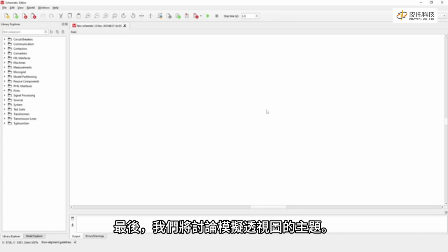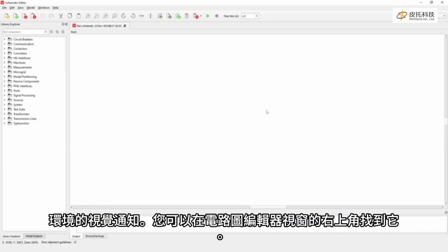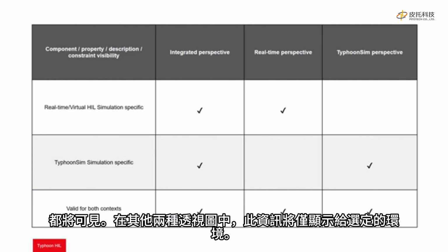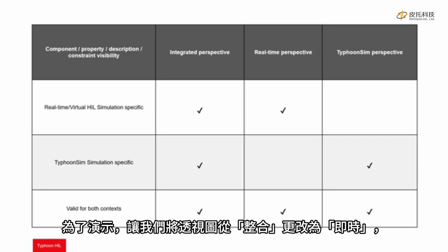The Simulation Perspective Chooser lets you focus on a specific context without receiving visual notifications from other contexts. You can find it in the upper right corner of the Schematic Editor window. There are three available perspectives to choose from: Integrated, Real-Time, and TyphoonSim. In the integrated perspective, all components, properties, descriptions and constraints for both real-time/virtual HIL and TyphoonSim simulation will be visible. In the other two perspectives, this information will be shown only for the chosen context. If you don't have a linked TyphoonSim license, your perspective will default to the real-time perspective.